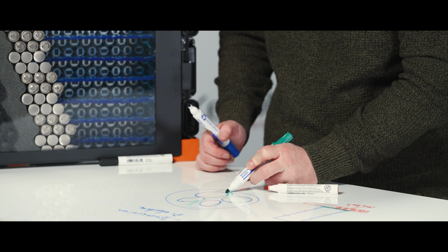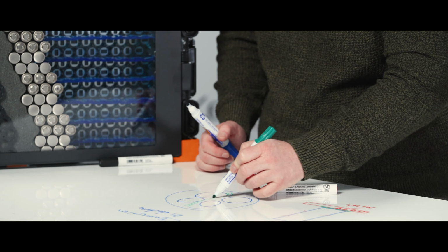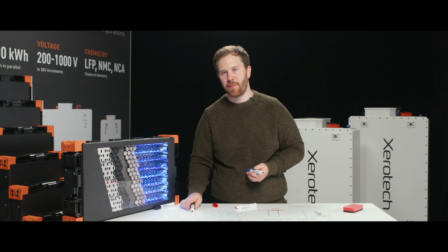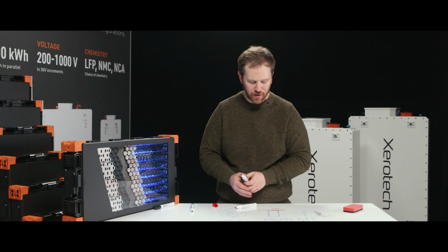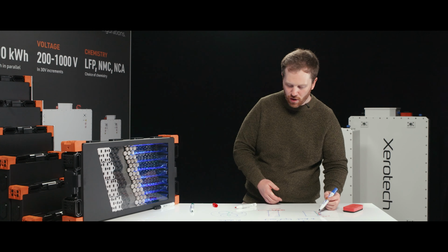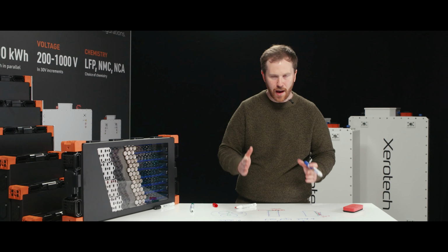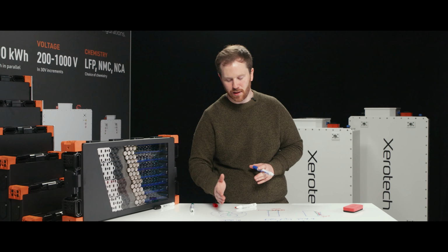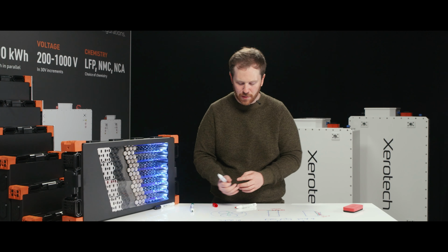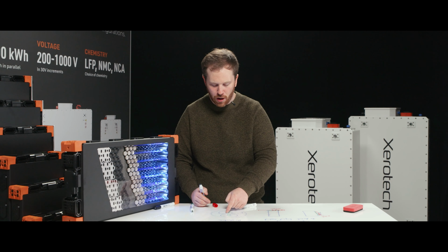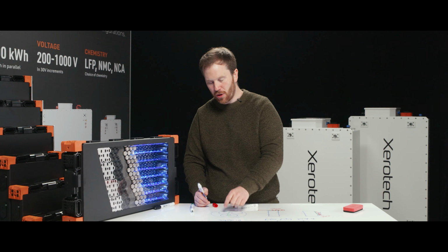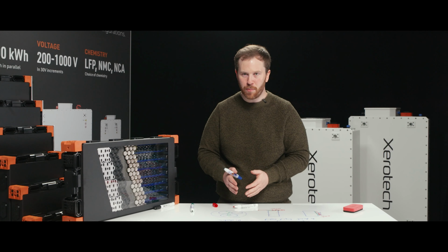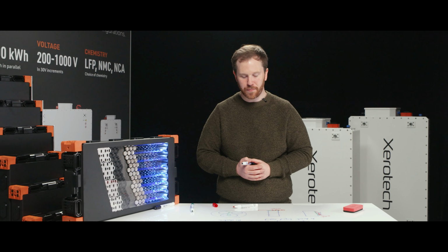So you basically get perfect angular contact around the battery cells. This was a big problem, for example, in the early Tesla Model S days, trying to get an extruded aluminium duct in between the cells and have a squishy rubber thermal interface material to contact the cells. So if you've got a cooling system that can inflate and fill all of the space perfectly, ensuring perfect contact area, and is also extremely thin, you end up with a very good cooling system.